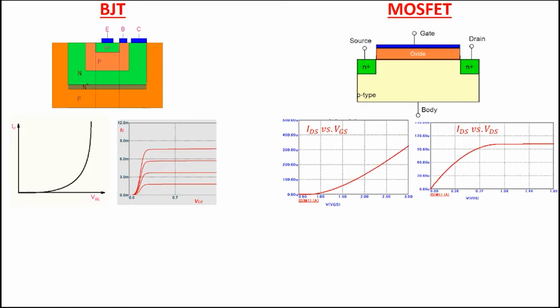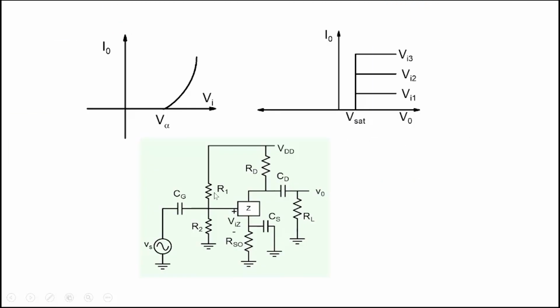All right, and we saw earlier that these are not ideal transistor characteristics, but if we bias a transistor here, and similarly bias a transistor somewhere here, then by the methodology that we had discussed earlier, we can build amplifiers. All that we need to do is take that hypothetical element called Z in the last lecture, take it out and substitute it by a transistor, bipolar or a MOSFET, and our amplifier would work and amplify the signal that is shown over here. All right, so let's stop here.